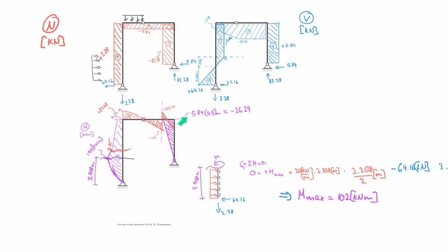Similarly, the moment diagram down here relates to the shear force diagram, just like we learned before, where the shear force is the derivative of the moment or vice versa. Just be careful when you follow your integration logic, right? Because also you could say that your moment is the integrated shear force. Be very careful when you go down that route because you don't want to forget about the integration constant here, which is the concentrated moment at that location.